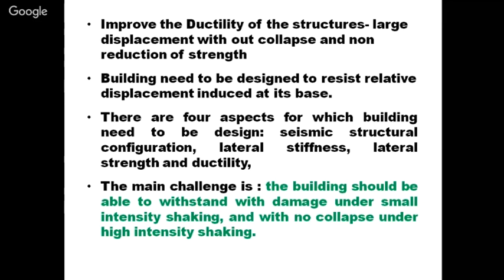The building needs to be designed to resist the relative displacement induced at its base. Another design principle is the large displacement which is induced by the earthquake at its base. The building needs to resist those displacements. That force we call the base shear force.